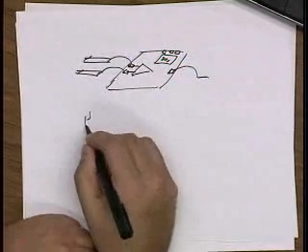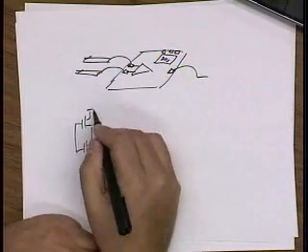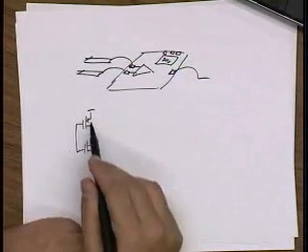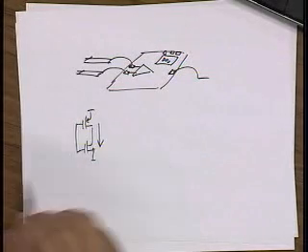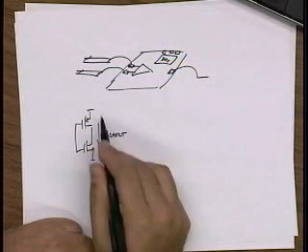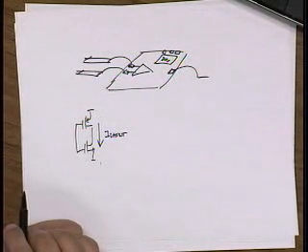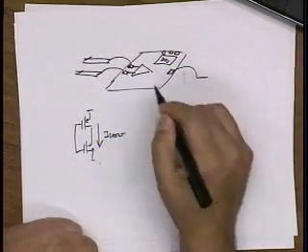During transitions, inevitably, you get short circuit currents, right? Ideally, these two switches are never on together, but we all know there's a time when they both turn on, and if these are big transistors, they short the supply, and so a huge current flows from VDD to ground. Okay? And so all these currents are being drawn from my power supply.